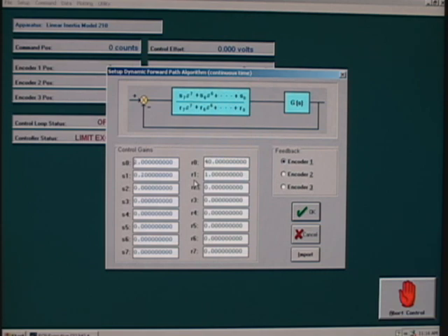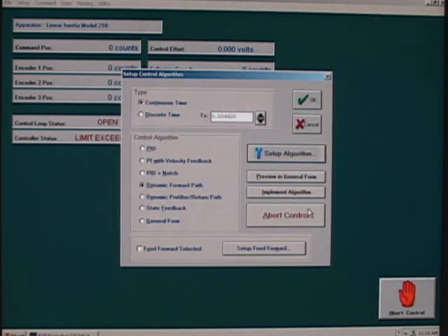It was actually 0.3. So if we have a gain of 0.3, then we would have 0.3 times 10, or a gain of 3. This would be then 0.3, and our denominator polynomial, which are the R coefficients. R0, I believe, was 35 for our phase lead pole location, and R1 is a monic polynomial. We can then say that that's okay.